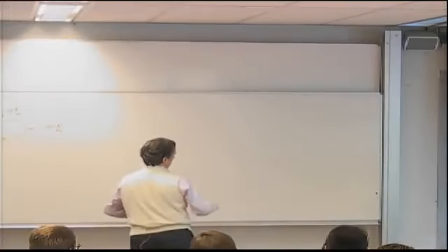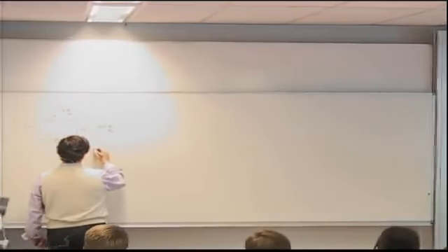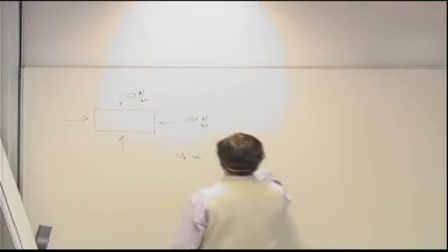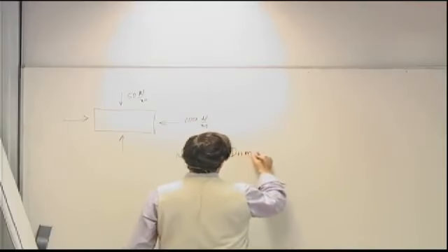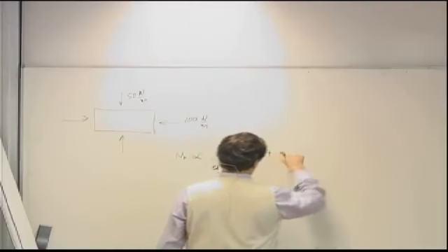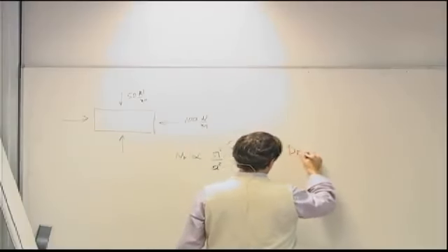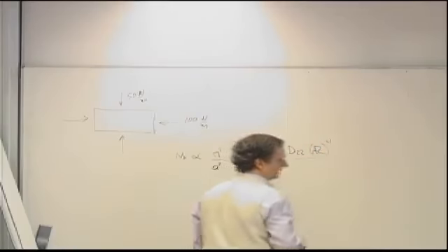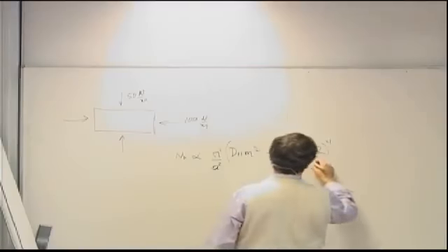If I isolate from the bottom equation the terms that involve m, basically Nx0 is roughly, I don't remember by heart, but I had better, pi squared, D11 m squared over a squared plus D22 aspect ratio to the 4th divided by, right, m squared.